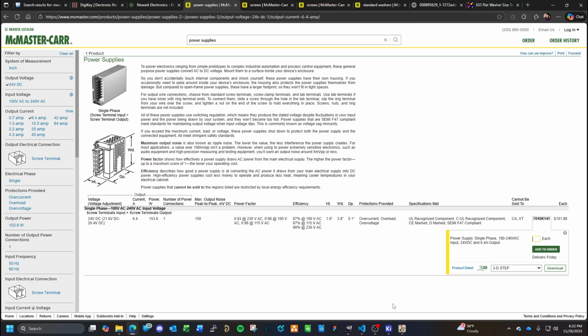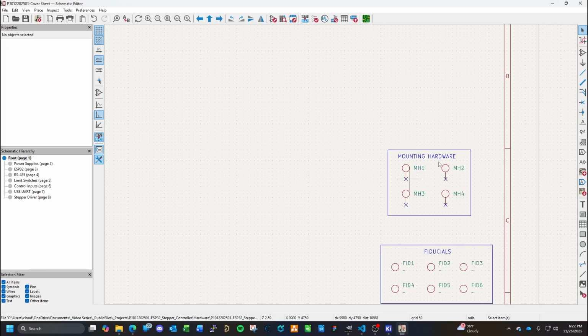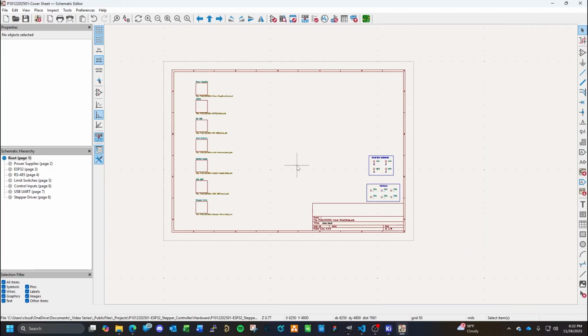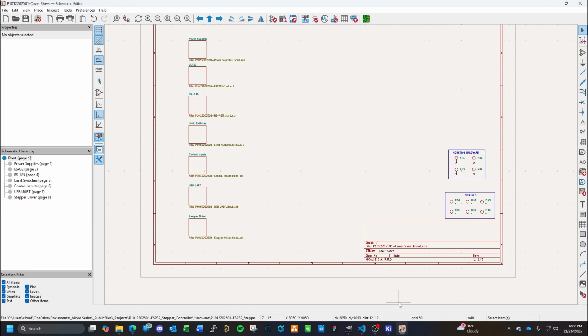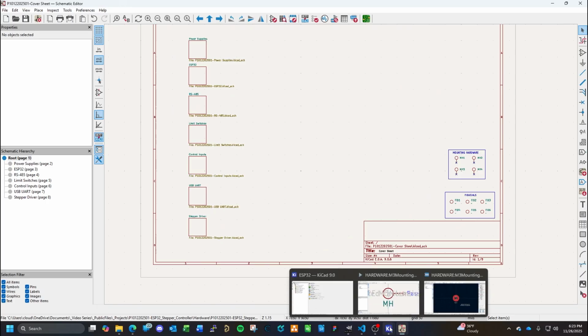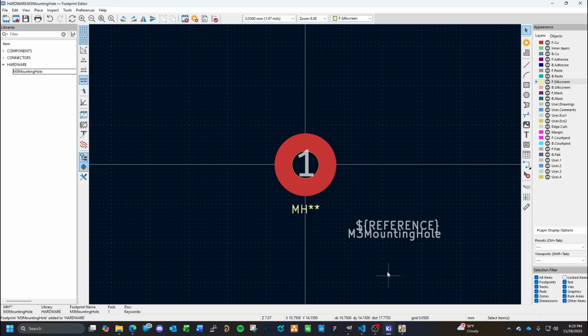So for our design, these would just be non-connected. But again, I left them as pads so that you could electrically connect them to chassis ground or physical earth, depending on your needs. I just wanted to cover that before we got too far along, because it's way too easy to ignore things, and I don't want to ignore things because that could put you at risk.